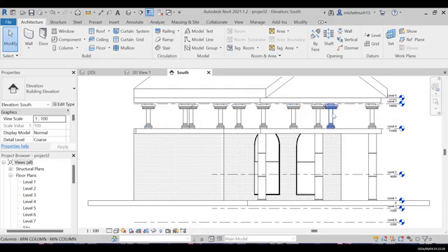Because if the level distance is higher than the one for the column, the top of the column won't be attached to the rest of the column, right? You know what I'm saying, right? So that's why I created level 7 here, and I put the roof on level 5, right? So I'm gonna show you how to do the staircases for this small house.